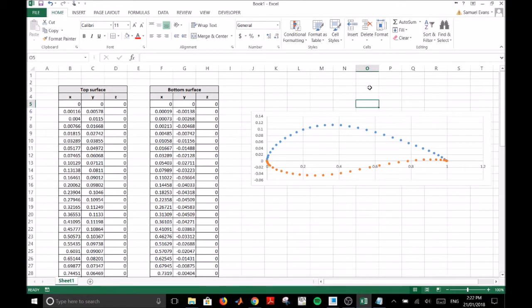So in terms of making our own custom geometry, you should be well familiar with making simple features in the Creo sketch palette or either importing coordinate systems or data from equations. But the third way we can make geometry is by importing custom points and modifying a spline curve to fit those points. So this is useful for many applications, such as airfoils.